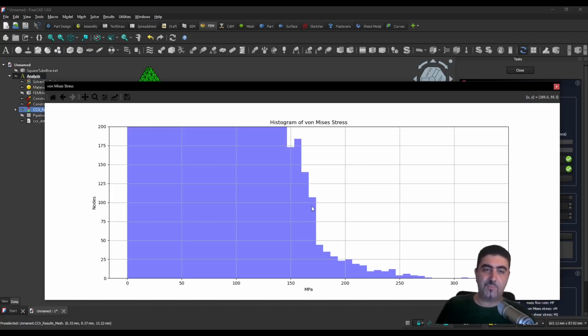So I would be inclined to say that the real value for the stress, the one that I should be worried about as an engineer, is somewhere around the 160 megapascals range. Now, what would that tell me? Well, that would tell me that, for example, this very part in particular would handle the 20 kilogram load for a few times, but not forever, right?